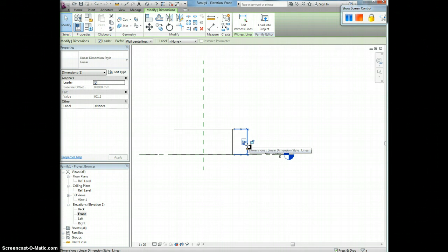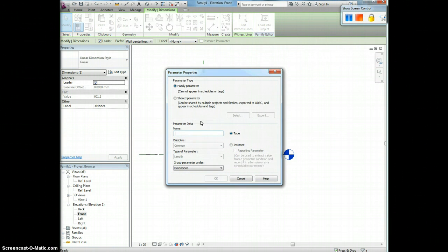The next step is that I'm going to make this dimension a parameter. The way of doing that is on the spot. After you create it, you can actually change it. Instead of finishing all the dimensions and then changing one by one, you can create one dimension and change it. When you click on this, you will notice something here. Do you see this label? Pull it down. You can add parameter. For example, this parameter is h. You can use a full name called height. Spell it as height.